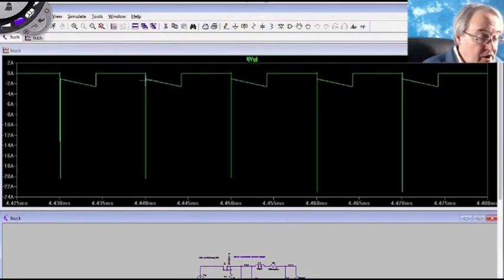When the transistor is on, the current follows the inductor current, again with a minus sign. When the transistor is off, the transistor current is 0, and so the VG current is 0 also. We also have this current spike here, which is caused by the reverse recovery of the diode and by the transistor and diode switching times. This is another source of loss called switching loss, which we're going to study in the next short course of this course.